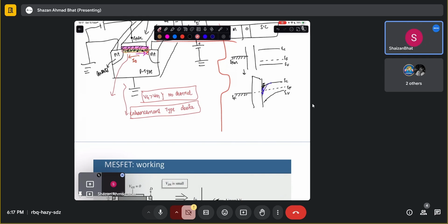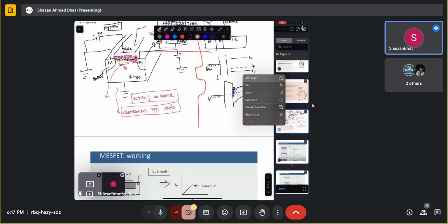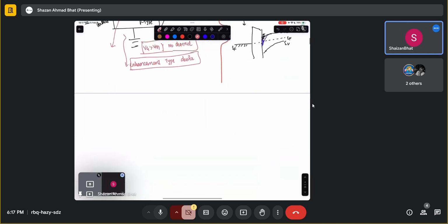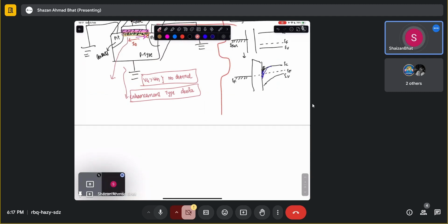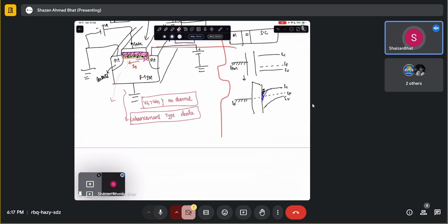It's not already there. Now, jumping into the MESFETs, what is so intriguing about MESFETs is that they are mostly depletion type devices, and you don't have any oxide between the gate and the drain. There is something called a Schottky barrier formed. One more thing you might know from your previous studies is that this is basically a diode, so these are connected and they are all grounded. You want these diodes to be reverse biased so that the current does not flow in that particular direction. That is the reason the current likes to flow in this region. It does not go towards this region.